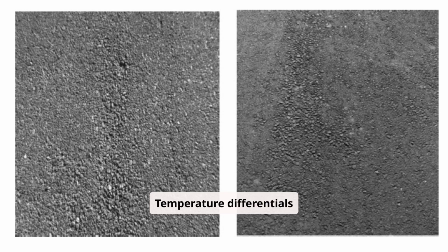Temperature differentials may not allow proper mixing of aggregates. If the mixture is delivered at low temperatures, it is an indication that the mix might not have adequate time for compaction, which results in a segregated mix. Handwork behind the paver screed generally involves depositing asphalt material on top of the mat in either thin layers or individual aggregate particles, and is therefore detrimental to pavement appearance.